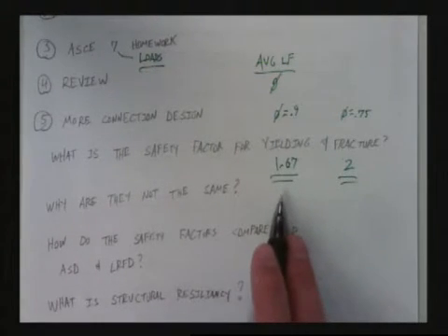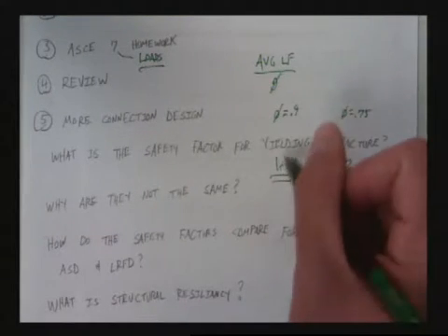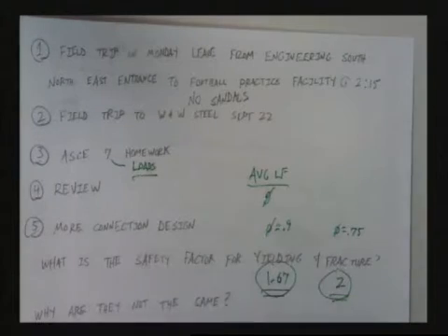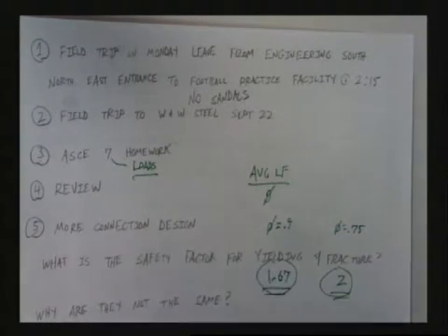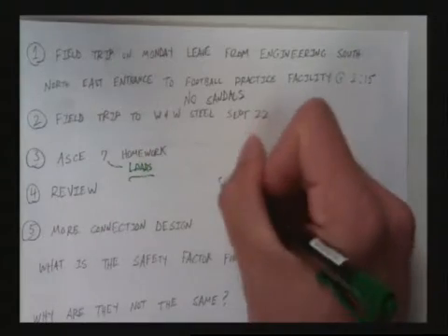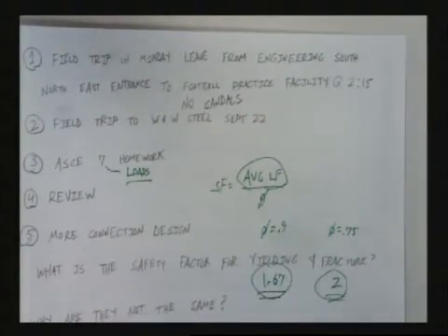Now, when it comes to LRFD, do we actually have hard safety factors? No. So what's our safety factor dependent on? The ratio of live load to dead load. That's right. The ratio of live load to dead load. Why is that? Well, it's because our dead loads we're much more sure of, right? And our live loads, we're less sure. Remember when we said average load factor, right? Safety factor is equal to average load factor divided by phi, right?